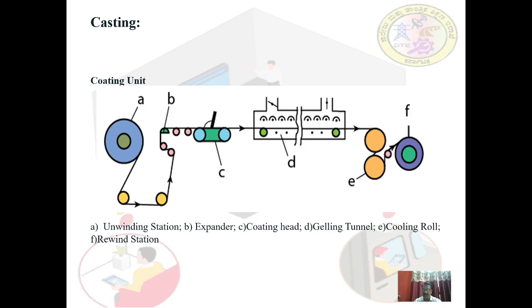The cooling effect must be high enough so that no adhesion between the individual layers occurs. The cooling is maintained by two water-cooled, corrosion-resistant drums. Next is about coating of the plastic material over paper or textile material.